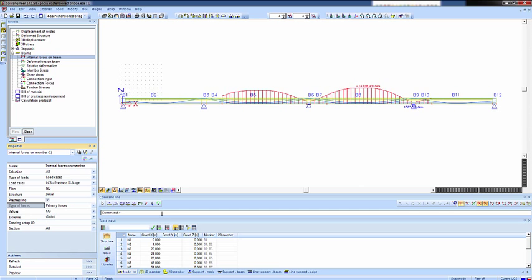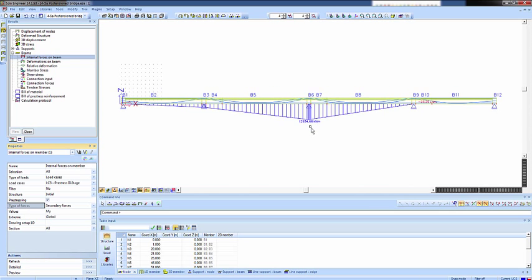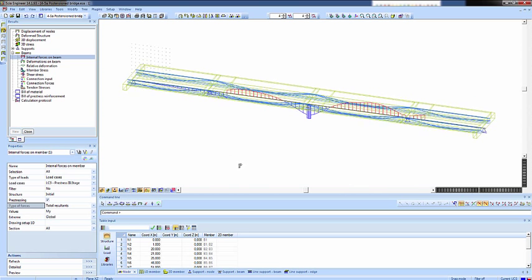But, very important, you also have secondary forces. Due to applying the prestress, you're creating a hyperstatic structure. And if you have a hyperstatic structure, then you're going to lose a part of your moment because due to your prestress, the structure wants to deform. But this deformation is not allowed because you have supports. And the supports give a reverse moment because they block this deformation. And this reverse moment, those are the secondary forces. Now what you take into account is the combination of the prestress and the secondary forces. This is what you can see here.